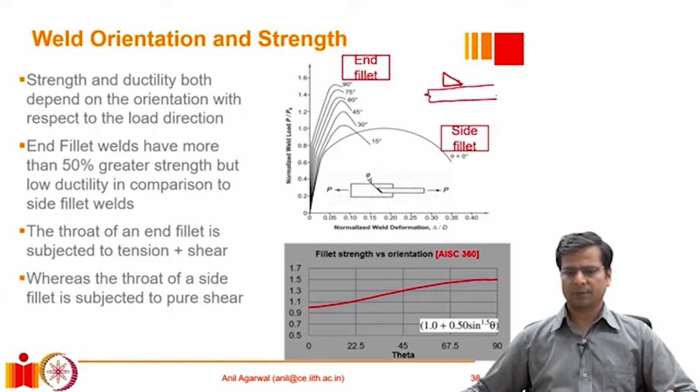This is one plate to which it is welded, and let's say this is another plate to which it is welded. I am creating some gap in between so that we can appreciate the difference. Now let's say the bottom plate is restrained at this location and the top plate is being pulled. If that is the situation, imagine how the force would get transferred from this plate to this plate. And for the sake of symmetry, let's put another weld on the other side so that there are no questions about the possibility of opening of the root. Let's say this is the system.